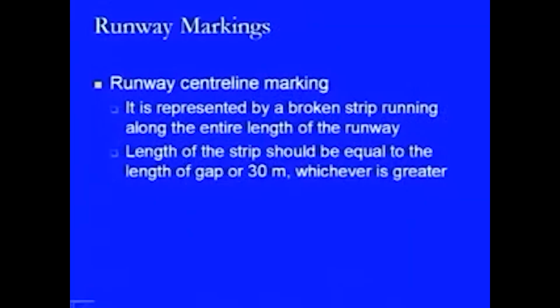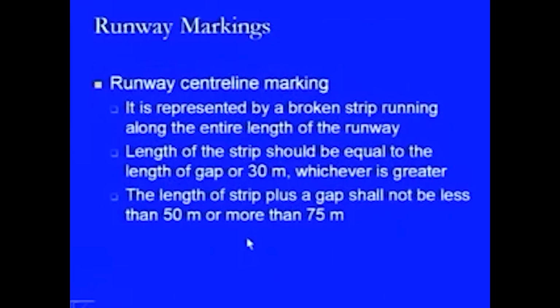The length of the strip should be equal to the length of the gap or 30 meter, whichever is greater. So, that is the way this center line strip is provided. The length of the strip plus a gap shall not be less than 50 meter or more than 75 meter.